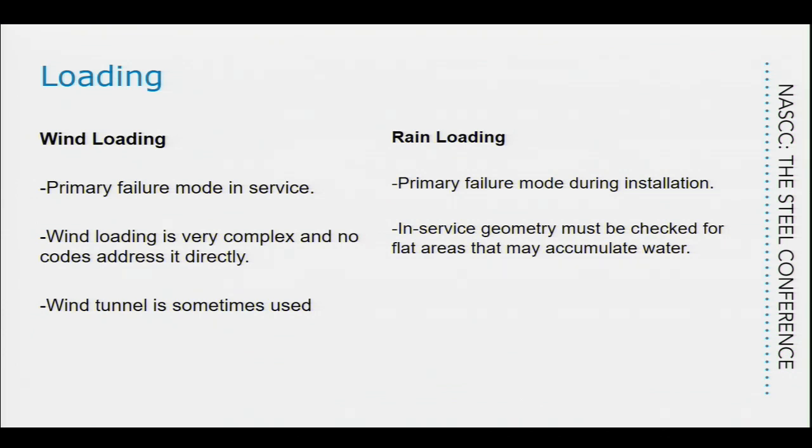So we have to try and extrapolate from the codes that we do have and try to get close to how the membrane structure is going to react. Some of the membrane programs are starting to do like a virtual wind tunnel test. It's not entirely there yet. It's very complex when you get the geometries that we get.